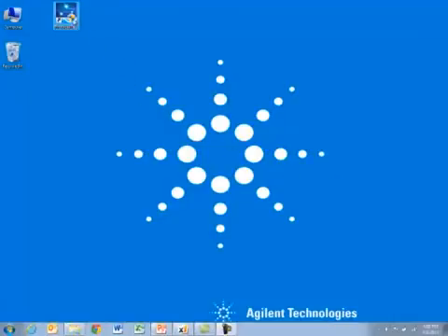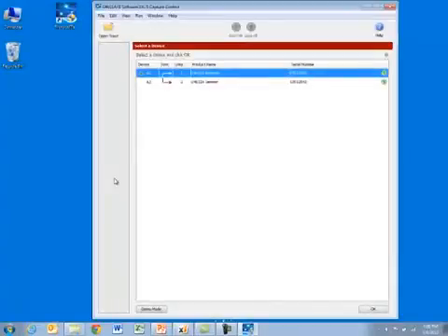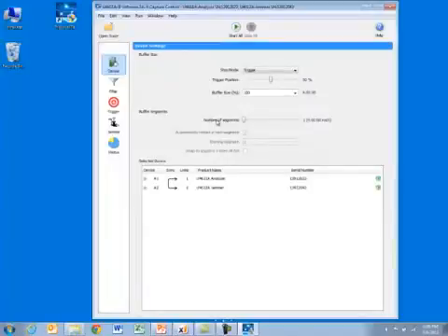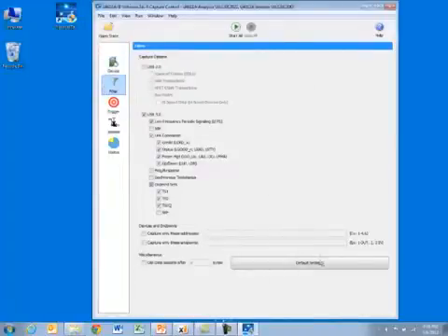So now I will start up my software to do this demonstration, and as I bring up the software, it immediately recognizes I have an analyzer and a jammer on the link. I open it up. These two units are connected together, so they're operating as one unit. I am capturing packets with the analyzer. It has a 9 GB capture buffer, using all of that buffer, waiting for a trigger condition. In the filter mode, I'm using the default settings, which filters out idle conditions and skip messages, pings, response, and isochronous timestamps. Maximize my buffer a little bit more.